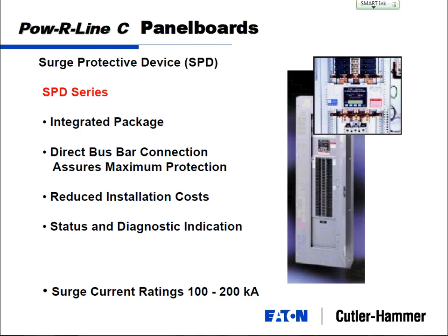There are two kinds of transient voltages. The most obvious one, when you talk about plugging your TV in, is externally generated transient voltages, the most common of which is lightning. If lightning hits the power cables across the street from your house, once it gets on the power cables, it's going to shoot wherever those power cables go, all the way down into your house, through your panel board, into your TV. That's going to send a big voltage spike through the system, and without protection it will go all the way into the circuitry of your TV.